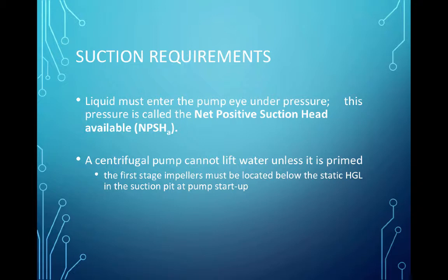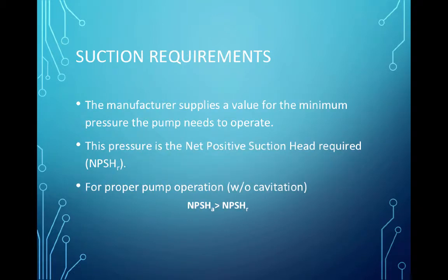When you shut the pump down, you're going to slowly close the discharge side valve while the pump is running, and then do the shutdown and complete closing the valve kind of contemporaneously, so that there's no way for air to get back from the discharge side and drain the suction side tube, so you don't have to prime it the second time. Sometimes it doesn't work and you have to prime it again anyway.